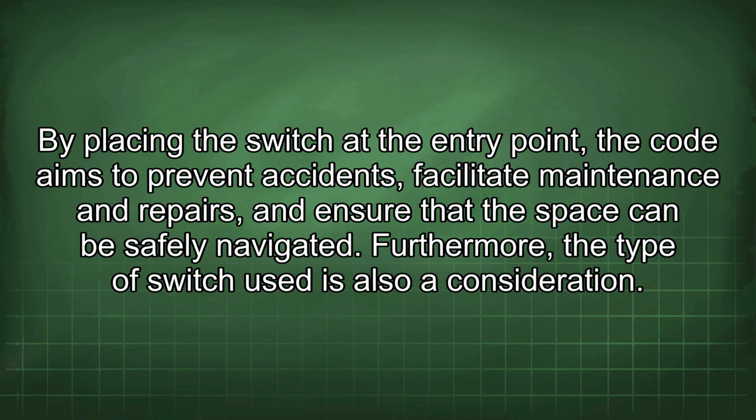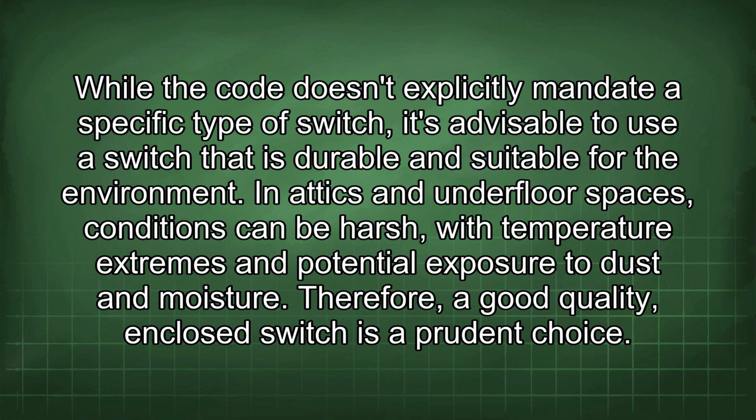Furthermore, the type of switch used is also a consideration. While the code doesn't explicitly mandate a specific type of switch, it's advisable to use a switch that is durable and suitable for the environment. In attics and underfloor spaces, conditions can be harsh, with temperature extremes and potential exposure to dust and moisture. Therefore, a good quality enclosed switch is a prudent choice.